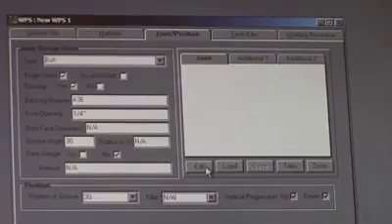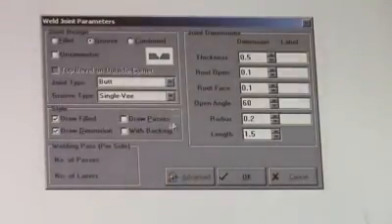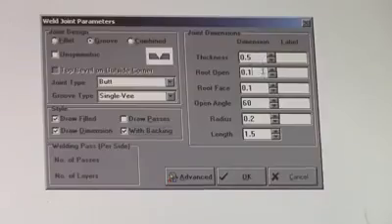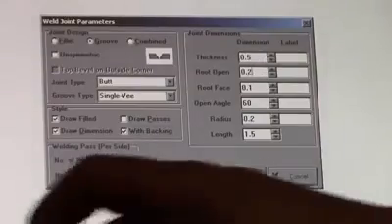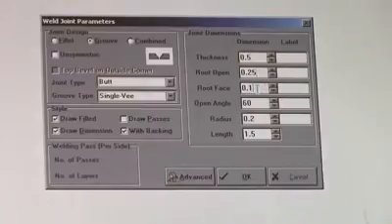This is going to actually ask you to draw the joint, so you go to Edit, Weld Draw. We'll go to the joint first with backing. Thickness 0.5, root opening, that's 0.25, that's our 1/4 of an inch. Root face, it's going to be 0. Groove angle 60, okay. There it is.